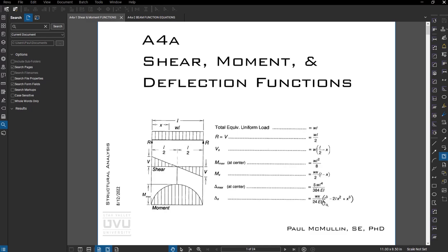When we're designing simple span beams with reasonably simple loading, which is frankly 90% of the time, we can use these simple equations to quickly get the max moment, max shear, and then size a member. So these tools become really effective. And if we have more complex loading, sometimes it's worth the effort, which takes very little effort, to simplify the loading. Maybe you are 5 or 10% higher in your moment and shears, but it makes for a really simple analysis.